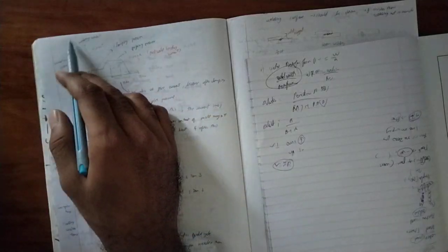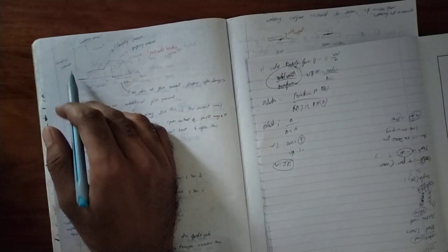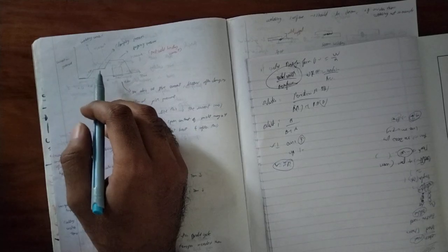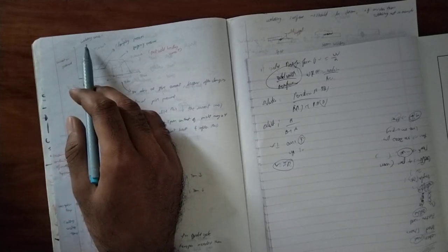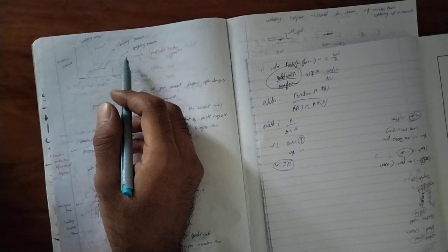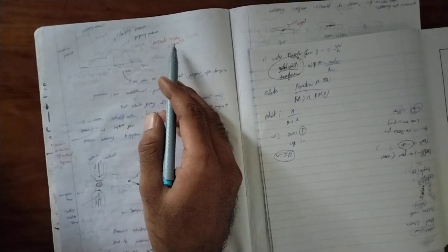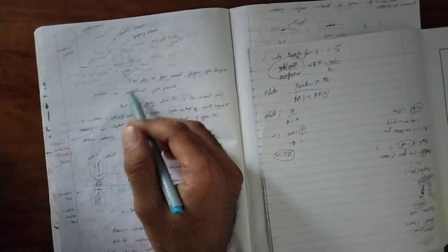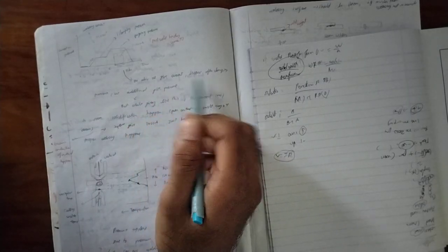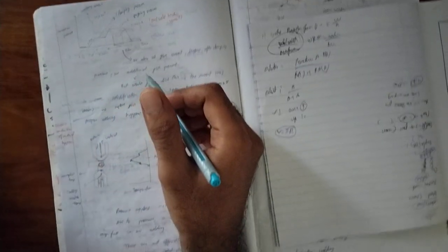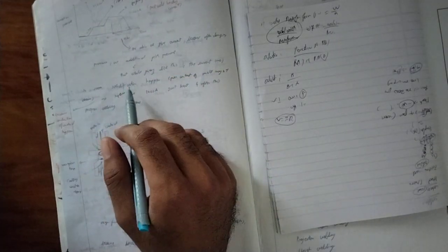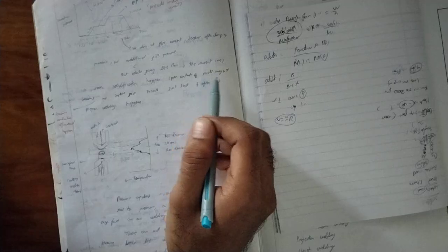So you can see here current and pressure. At the beginning we press and hold, and within a certain amount of time the welding current will be very high. Then post-weld heating current occurs. Here also we give current, because after clamping we give additional pressure. Otherwise solidification happens too soon and poor conduction of the metal may occur.